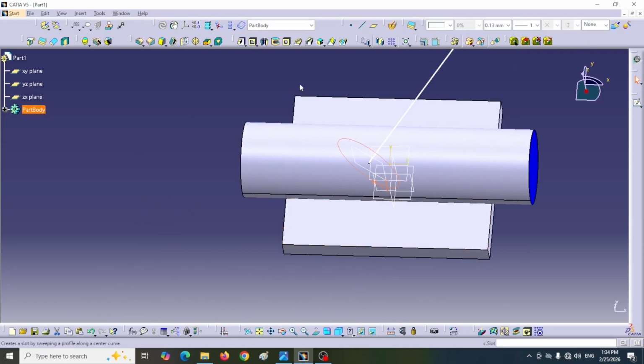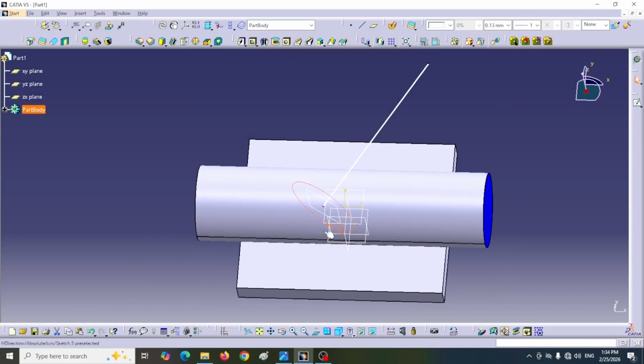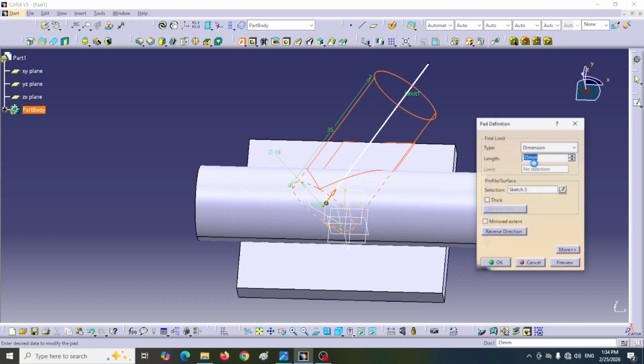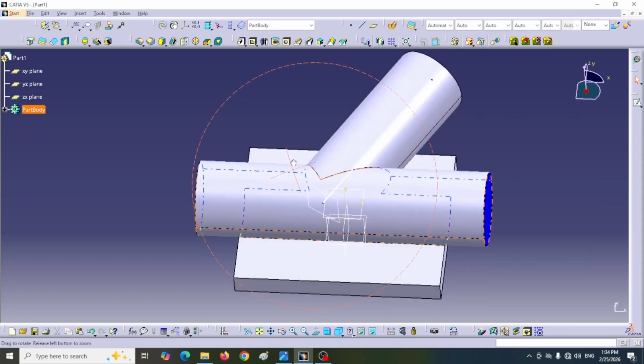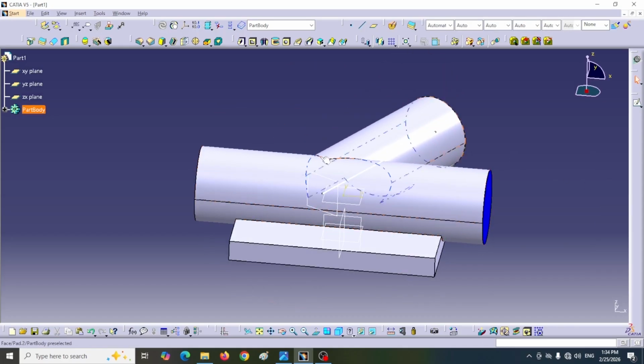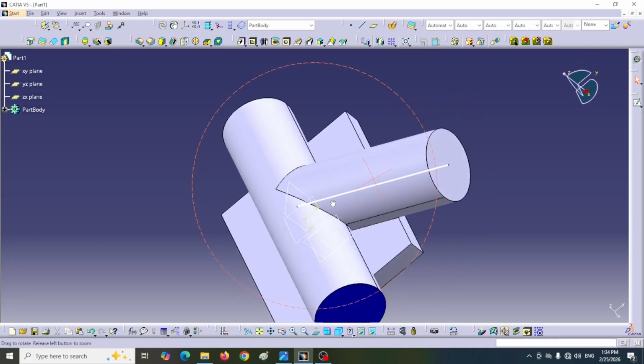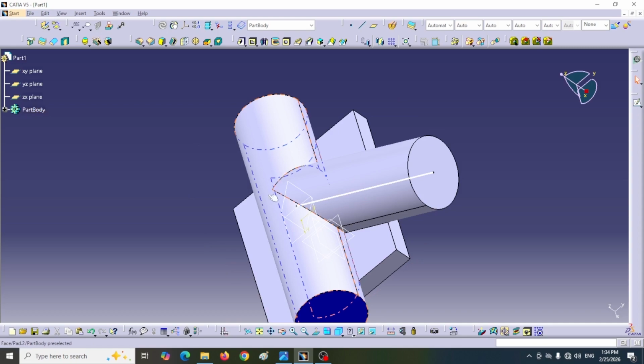But there is one issue. Since part of the sketch circle is behind the horizontal axis, after extrusion an extra material is created. Of course, I can remove it with the pocket tool. But this method is not 100% precise.